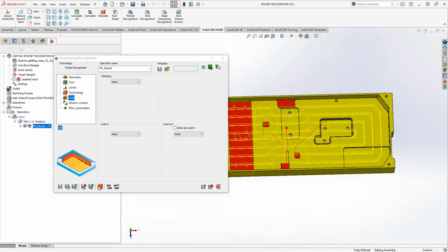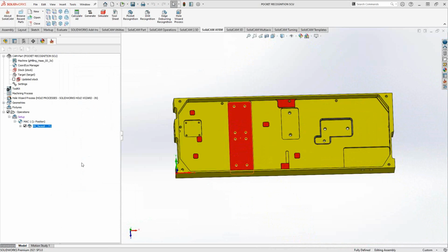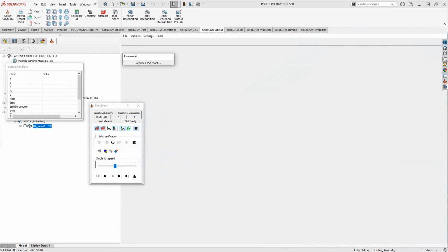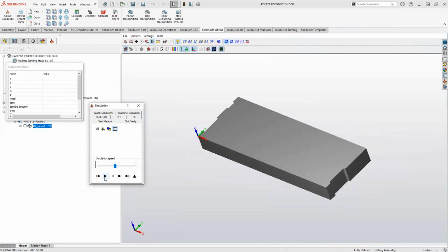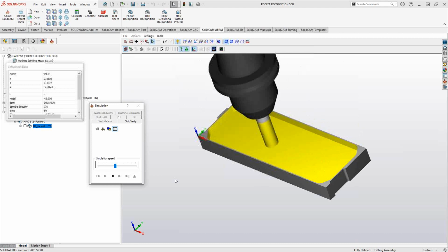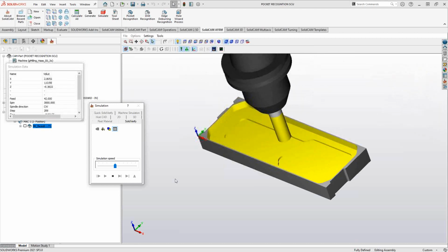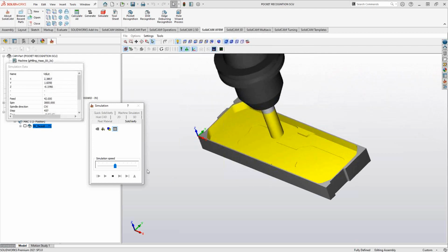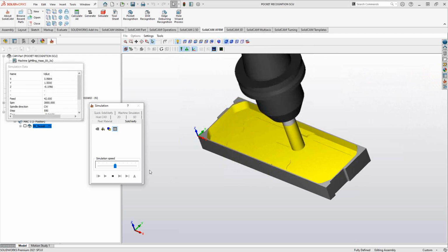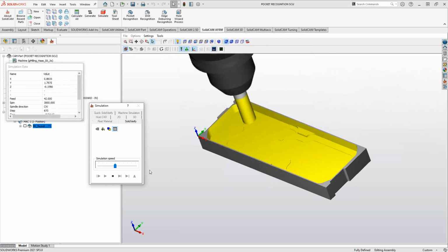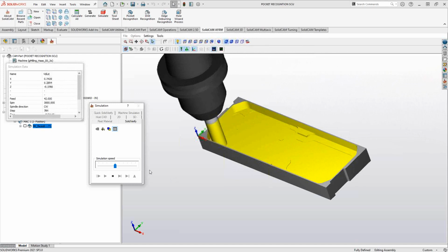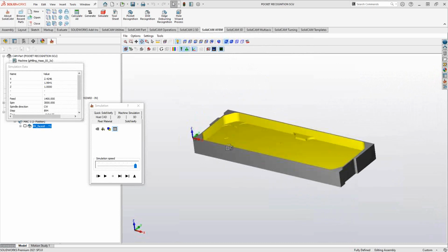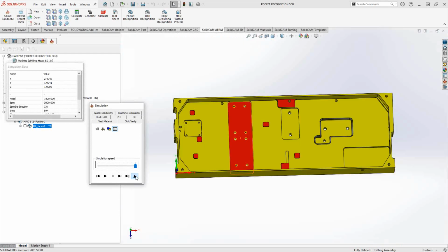And then as it gets a little lower, you can see it starts to generate pocketing toolpath for the entire part. If we take a look at that in Solid Verify, we'll see that it actually begins to do layer by layer different pockets. And there's the adaptive step down there because the 250 from the top left behind some material. And then we start to do some of those bosses there. Now, if I speed this up just to get to the end, you'll notice that it did not do those lower pockets. And that is because I defined the lower level.